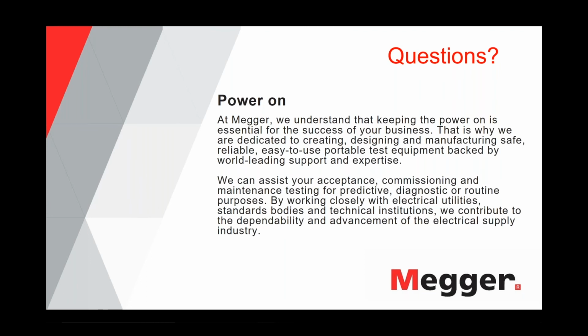All right, thanks. Javier, when testing a 15 kV cable, what are the 3 values of U0 to be used, and what exactly is U0? Okay, U0 is the operation voltage between the conductor and the concentric. So when we talk of 15 kV cables, typically the operation voltage will be 13.8.